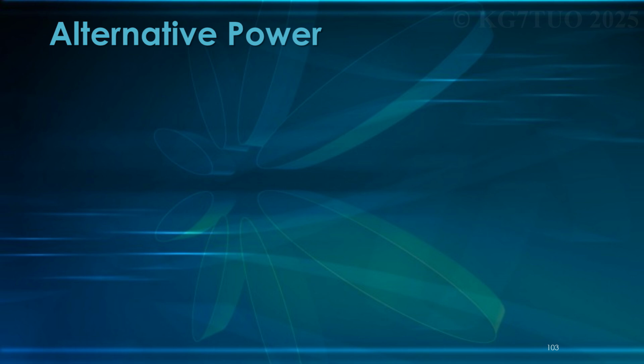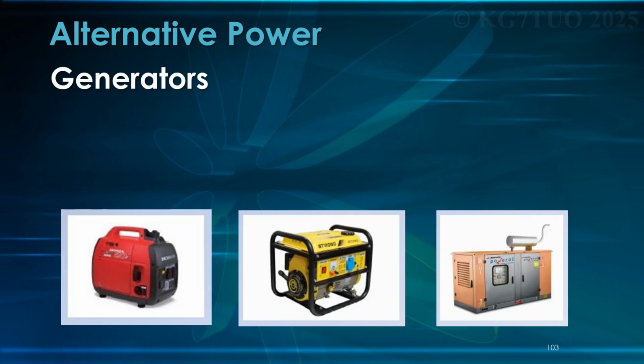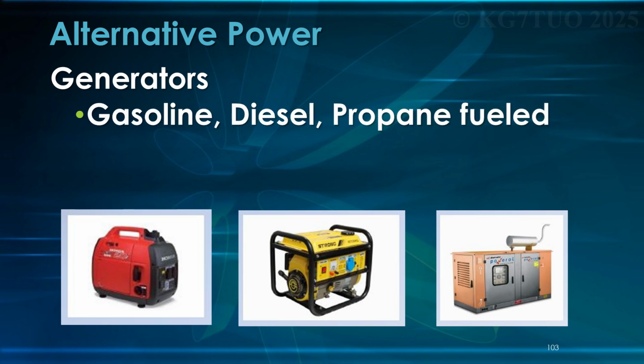So, alternative power, generators. You've got a portable generator on the left, a sort of portable generator in the middle, and a stationary generator on the right. You can have gasoline powered, diesel powered, or propane fuel. Some are dual fuel, they'll do gasoline and propane. That's probably the best solution. The big one on the right, very often they connect those to a natural gas line coming into the house. Sizes run from less than a kilowatt to over 10 kilowatts.